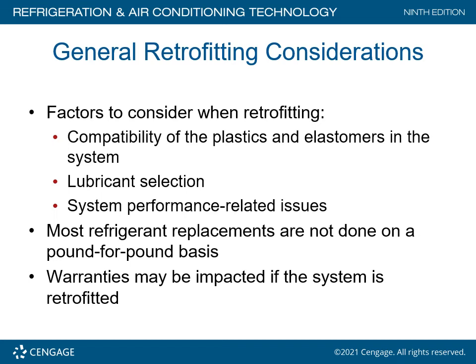But now here's the thing we have to be very careful about. Energy efficiencies will not match the coil rating versus the brand new unit outside. So it is always best, when you're changing out a system, to change the coil and the condensing unit as well as the refrigerant piping, because typically it's too small.